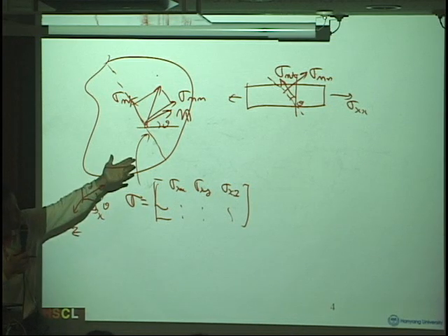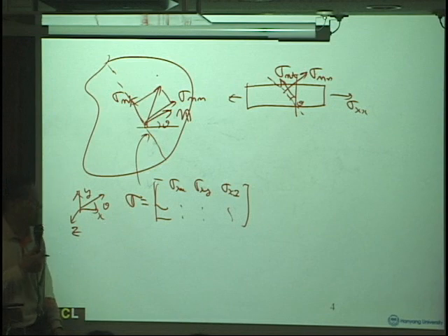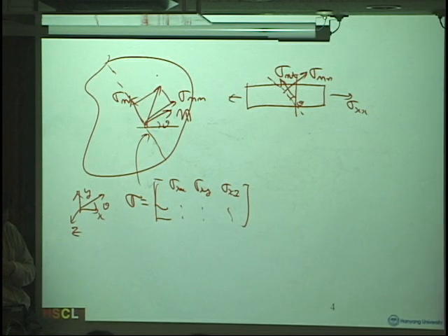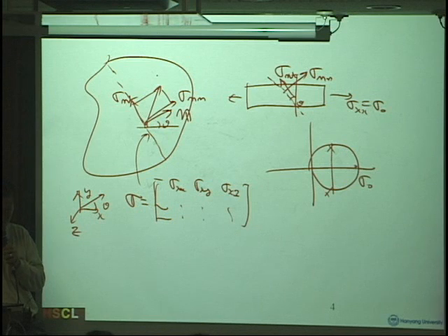We reviewed that one-dimensional case many times, and in terms of a Mohr circle, it's simply like that, right? So if this is a sigma 0, this will be sigma 0. And as you can see, the shear stress will reach maximum at 2 times 45, this is 90, right?